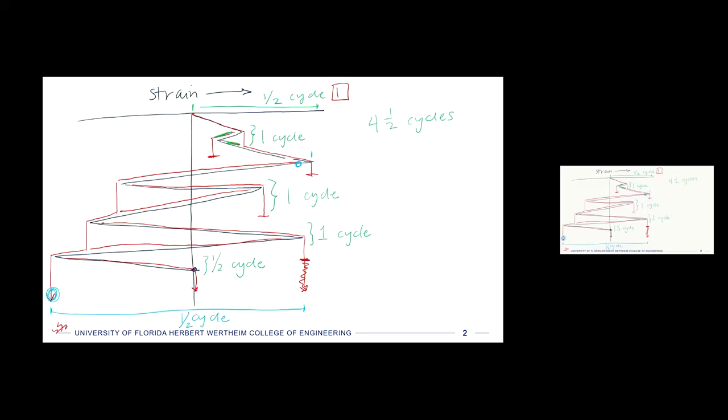So that's cycle 1 at that amplitude with that mean. Then we had the little one underneath that, so that would be the second damage accumulation phase. It's one cycle at a much smaller amplitude and a high positive non-zero mean strain in this case.